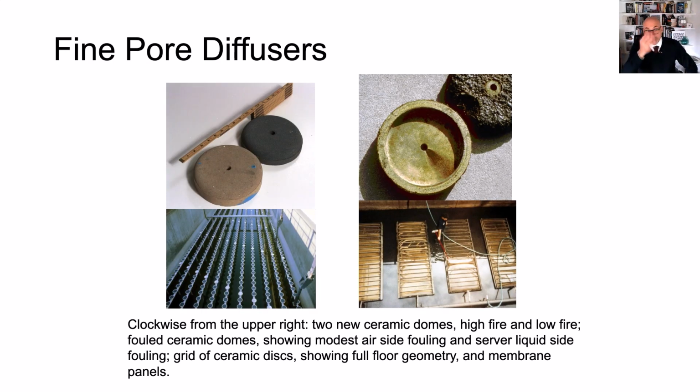So here are some pictures. Those are the old domes. The air comes in from the bottom and fills up the dome and goes through the porosity. Those had a lot of mechanical issues with the screw nipple that, if made of plastic, would just break and the dome would fall off. So a lot of those have been abandoned and replaced with the arrangement you see on the bottom.